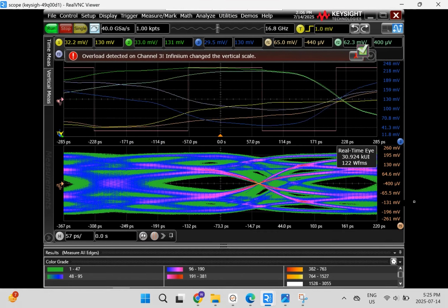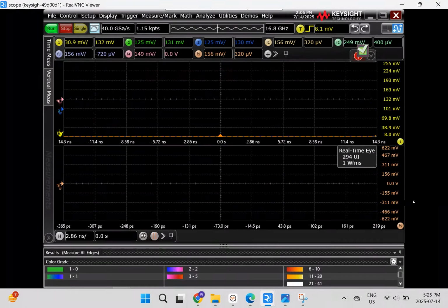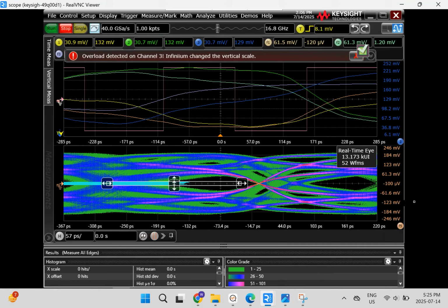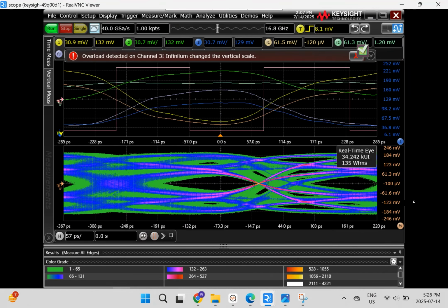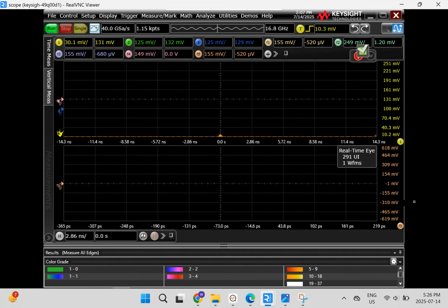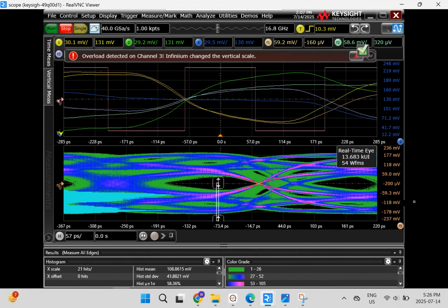height. So in the case of C5 conformance testing, we need an eye width of 0.5 UI and a height of 80 millivolts. And that's what this script is aiming for, and it should be able to generate this.